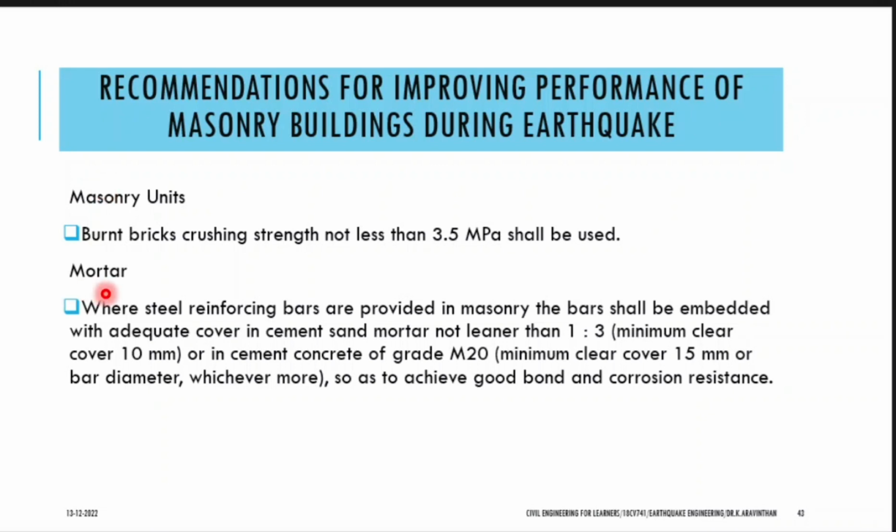Now, next one is mortar. You can use the mortar for plastering after brick masonry or for binding the bricks. The cement mortar should not be leaner than 1:3. Minimum cover of 10 mm is required. So this is for masonry.